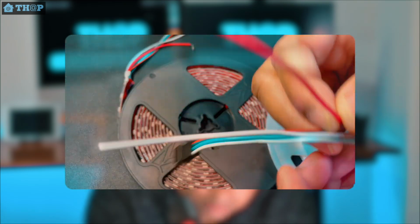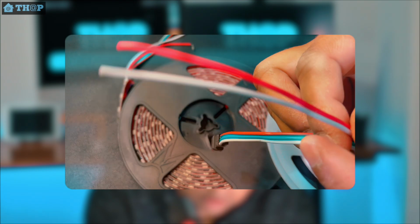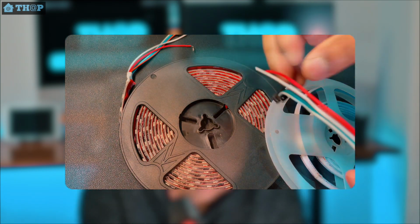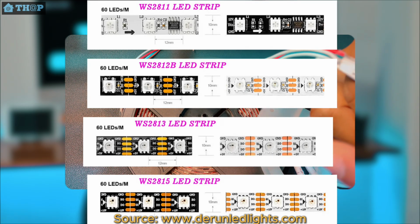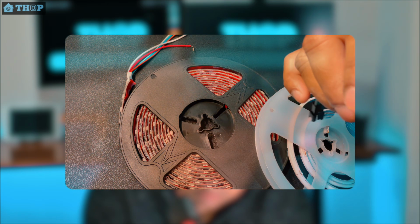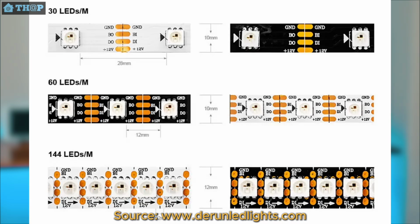I'm going to also use these 2 extra power injections. Depending on the length of your LED, you might need some extra power, and for each of these addressable LEDs there are certain subtypes. For example, the one I have here is called WS2811. You have got WS2812B, and you have got WS2815, etc, and there are some more versions, but these are the most common ones. And there are power ratings for each of these versions. It depends on the length of the LED and the density of the LED.